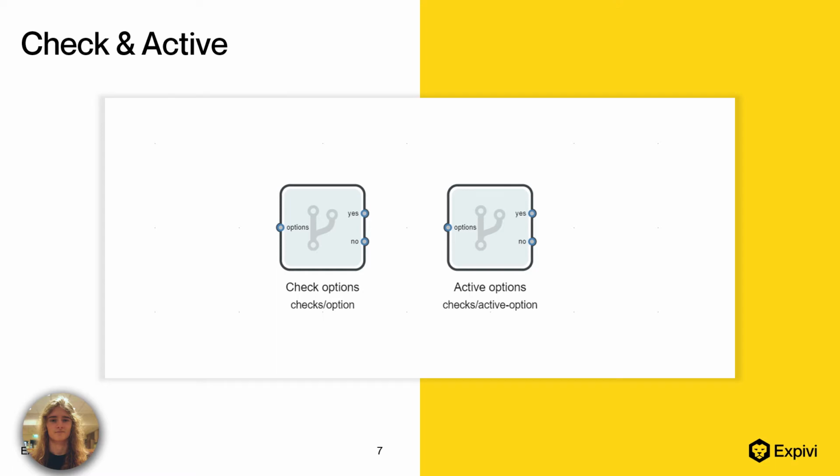The check option node only passes on the incoming signal if the specified attribute condition was responsible for generating the signal in the broadcast node. This type of check allows you to perform an action that isn't necessarily always true, but only after that specific event in the configurator has taken place.